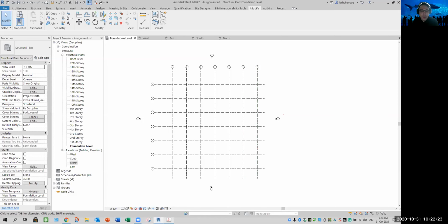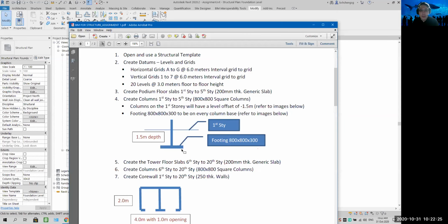By looking at your model, logically, this is a 20-story building. So for a 20-story building, normally we don't use footing; it cannot be used. Why? Footing is for buildings of maybe up to 3 stories or less, not 4. If it is higher, it must be a pile cap.